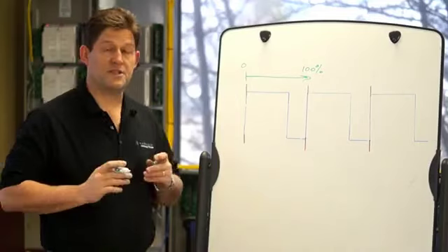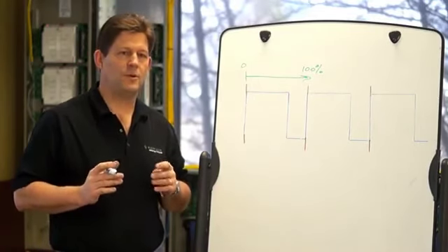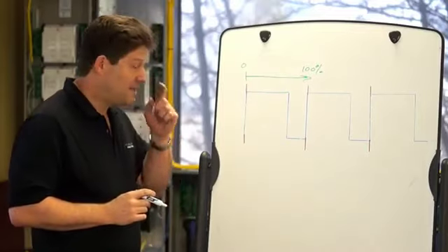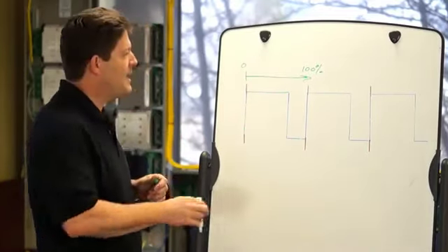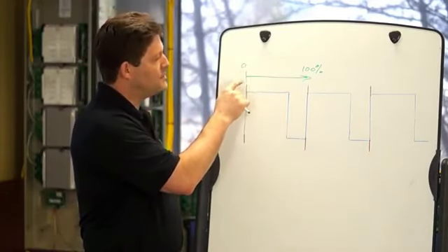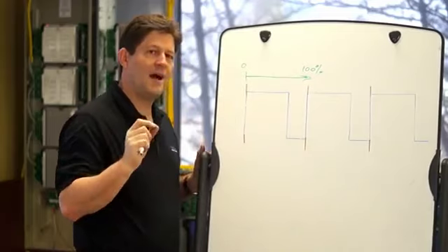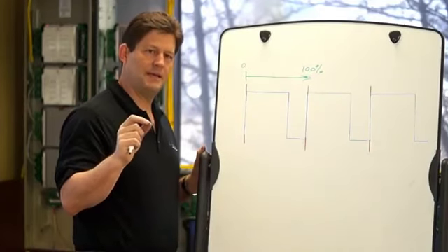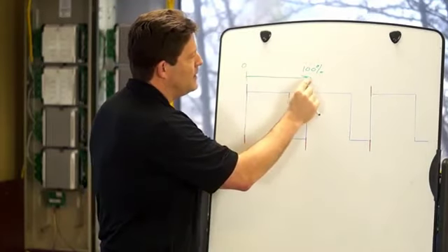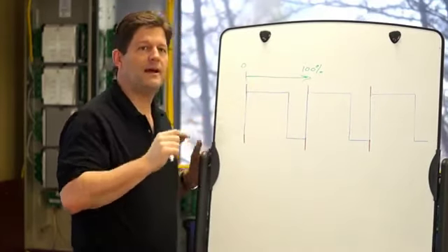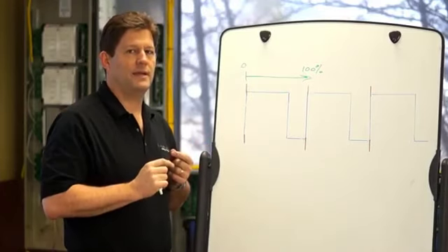Now, there is a standard that applies to dimming pulse width modulated controlled light sources, and that standard is actually opposite of what you might expect. Meaning that if I were to apply 0% of the time the voltage, then the light output is actually going to be at 100% and reduce down linearly to 0% when we apply 100% of the time the voltage. Opposite of what you'd expect.